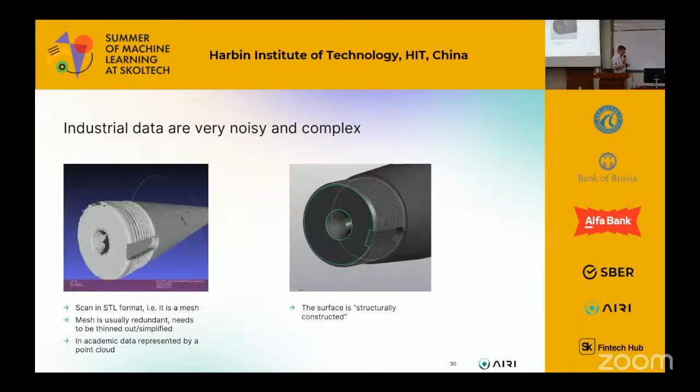At the same time, we have a lot of problems when we use 3D scanning. First of all, 3D scanning cannot see all the holes, all the elements inside some device, and there are some losses in the point cloud. And when the engineer takes this point cloud as the input, he needs to check and validate all this information, to reconstruct it as a good model, reconstructing the operations that are needed to create this model or this element.